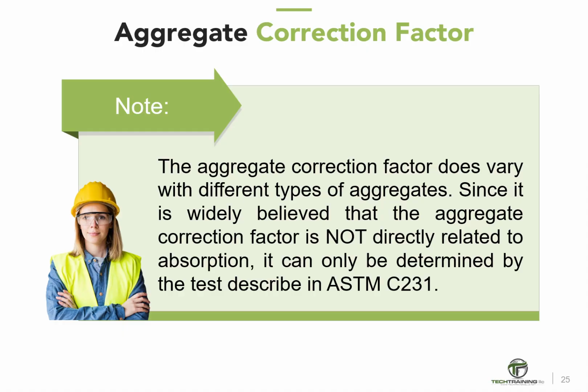The aggregate correction factor does vary with different types of aggregates. Since it is widely believed that the aggregate correction factor is not directly related to absorption, it can only be determined by the test described in ASTM C231.